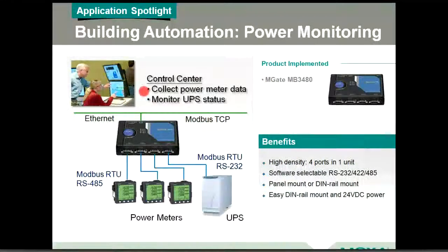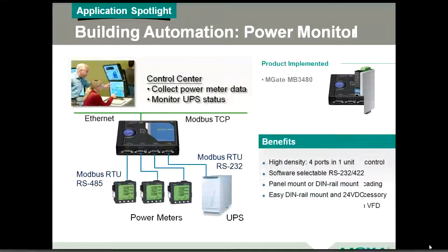And if this is merged within your group in a facility, whether it be a control room, even a data center application where there's critical power needs, a lot of the larger commercial UPS systems also have options, whether built in or an option card, to be able to monitor an uninterruptible power supply via Modbus. So great application on how you can instrument existing systems and bring that into your control center to be able to measure your energy usage and be more efficient at how you use that and find out what you can do to conserve energy.